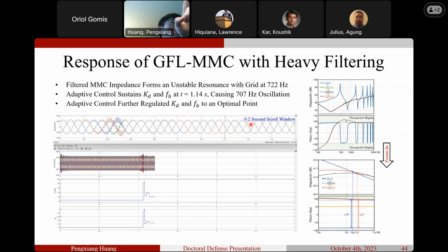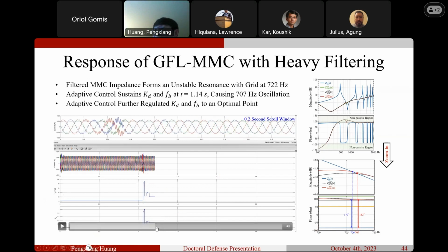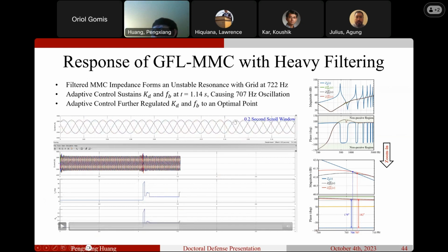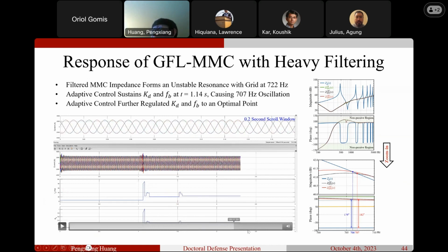But did you see a small right-side harmonic here? That is because this is still not the optimal point. If you keep watching, you see that small right-side harmonic keep increasing until some level, when it was identified. Compared with before, the right-side harmonic is increasing slowly, but finally it was identified as a small growing oscillation. Then you further tune your damper. What is the result of the further tuning? It gives you a completely stable system.